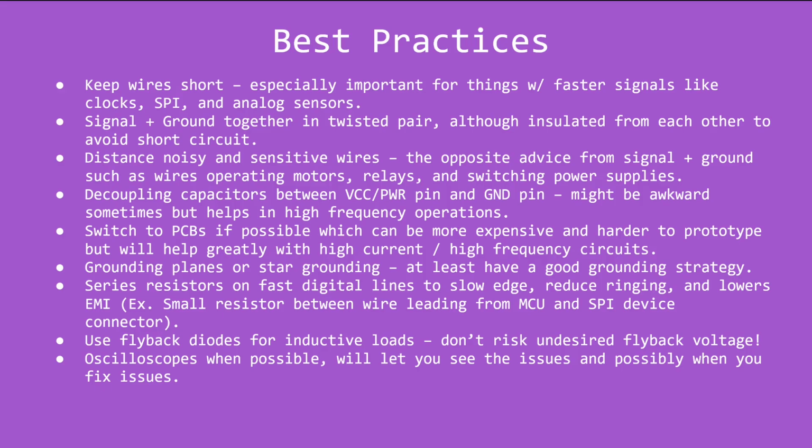For example, if wires are sensitive or noisy, then take the opposite approach and distance them from other wires. This includes wires operating motors, relays, and anything from a switching power supply. Use decoupling capacitors between power and ground pins with an IC. It might seem a little awkward sometimes, but it can help in high frequency operations. If possible, switch to PCBs for serious circuits, but obviously PCBs are their own category, harder to deal with and more expensive. I'm not even right now up to the point of being able to design my own PCBs.